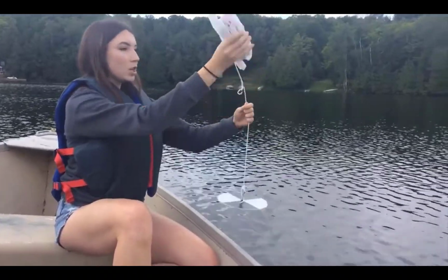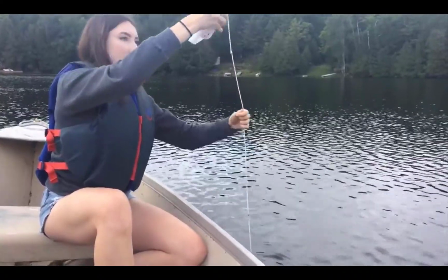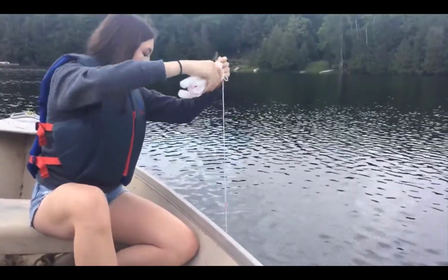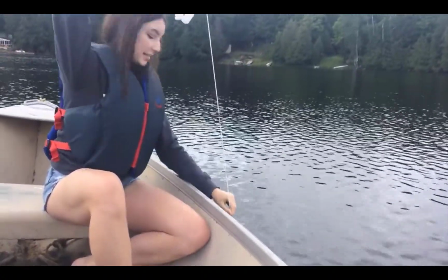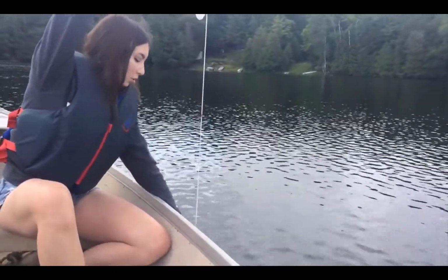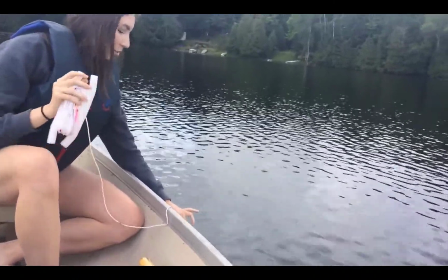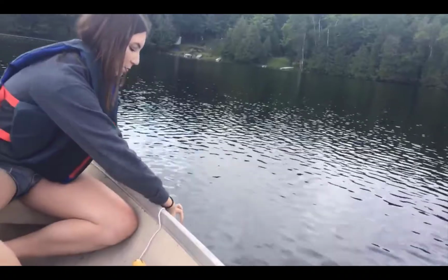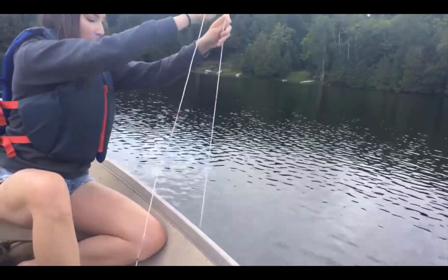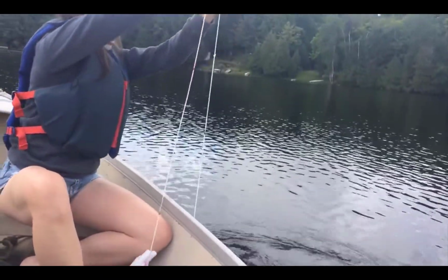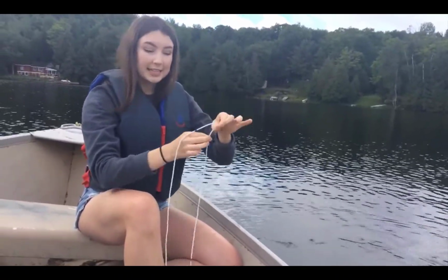So to perform the test, you lower the disc down into the water until the point that you can't see it anymore. And once it's reached the point where you can't see the disc in the water anymore, you pinch the rope right at the surface of the water. And once you have that pinch, pull it up a little bit to the point where you can just barely see the disc, and you pinch the rope a second time at the surface of the water. Then when you pull the disc all the way up, you have 2 readings, and the average of the 2 readings, right in the middle, will be your total Secchi depth.